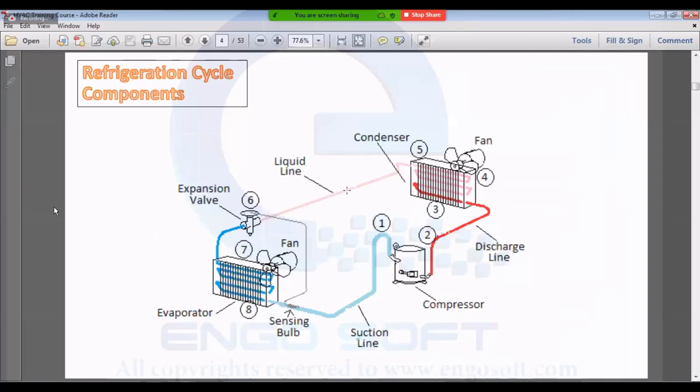So this is a more elaborate view of the circuit. This is the evaporator, indoor, and the suction line to the compressor. The suction line, as in the freon line, is the line which contains vapor refrigerant, the cold line. Then we add power through the compressor to the discharge line. This discharge line enters the condenser and the fan is cooling the vapor.